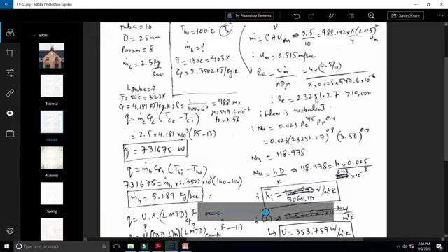So if you recall, if the Reynolds number through a pipe was greater than 10,000, we used to call that flow turbulent. Since it is 23,000, the flow would be termed turbulent. And for turbulent flow, the expression of Nusselt number would be selected, which was 0.023 Reynolds to the power 4 by 5 Prandtl to the power 0.4. There were two expressions, Prandtl to the power 0.3 and 0.4, depending upon whether it is getting heated up or cooled down. It is getting heated up over here, so you need to refer to that lecture.